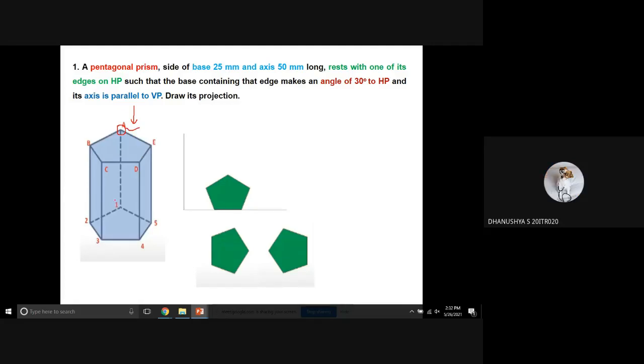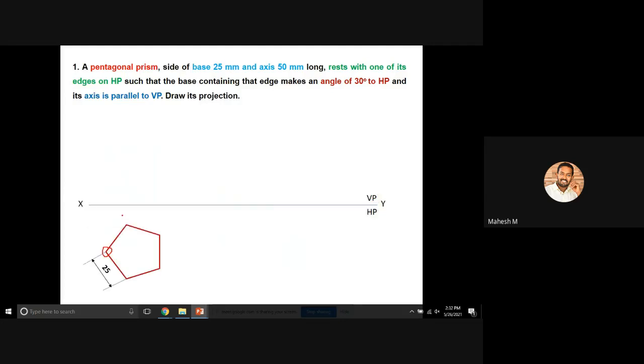Yes. So similar to that, you'll be having one more point. That is a hidden point. So the name of the hidden point is 1. Okay. Then what will be the name of this corner? A of 1, sir. A of 1. Okay. So if it is a prism, you will be having 2 names for a single corner. If it is a pyramid, you'll be having only one name because there are no 2 surfaces for a pyramid.